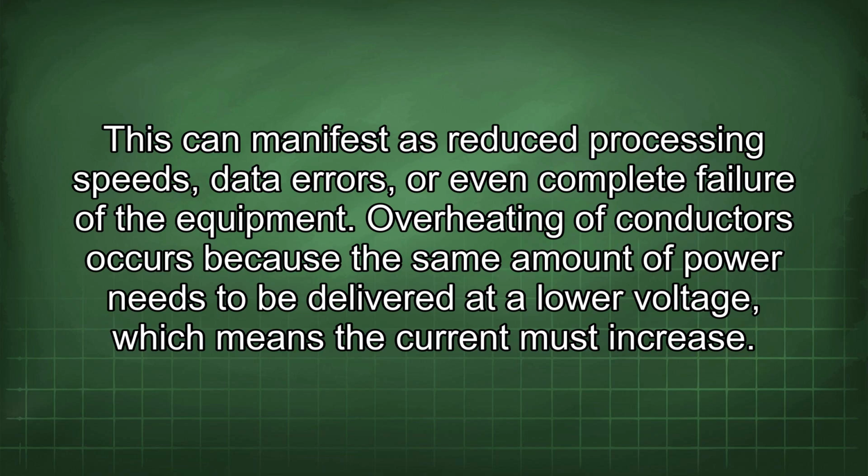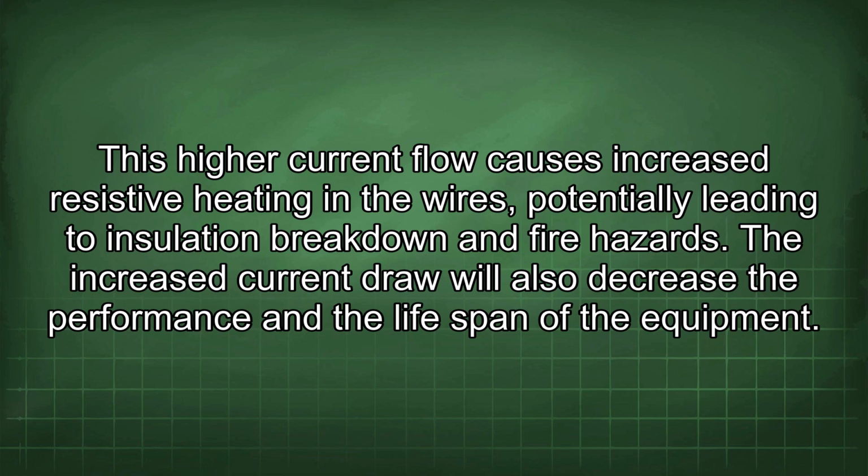Overheating of conductors occurs because the same amount of power needs to be delivered at a lower voltage, which means the current must increase. This high current flow causes increased resistive heating in the wires, potentially leading to insulation breakdown and fire hazards. The increased current draw will also decrease the performance and the lifespan of the equipment.